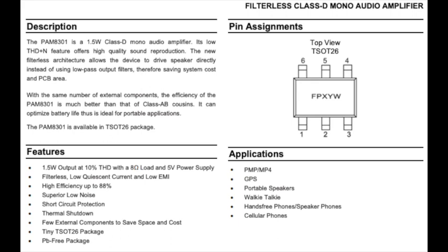The PAM8301 comes in a TSOT26 package, which has 6 pins. 2 of those pins are for your speaker connection, 1 pin's for your audio input, 1 pin is an active low shutdown pin, and then there's a power pin and a ground pin.